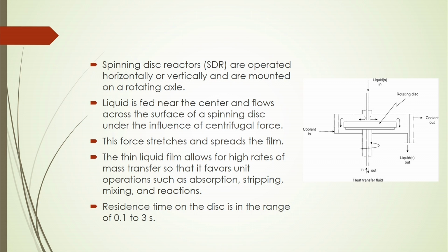This force stresses and spreads the film, and this thin liquid film allows high rates of mass transfer, so that it favors unit operations such as absorption, stripping, mixing and reactions, by getting more contact of the liquid with the surface area through uniform distribution of the liquid, and also more uniform mixing of the phases and interfacial transfer.